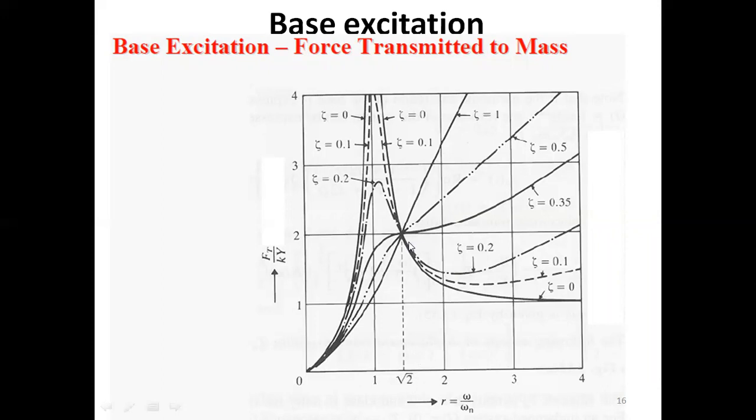However, for less damping ratios, you could see here that after a frequency ratio of almost 2.2, afterward the force transmissibility would increase. However, for an undamped system, where zeta is equal to 0, you could see that if the frequency ratio is further increased, the force transmissibility would be always 1 at higher frequency ratios.